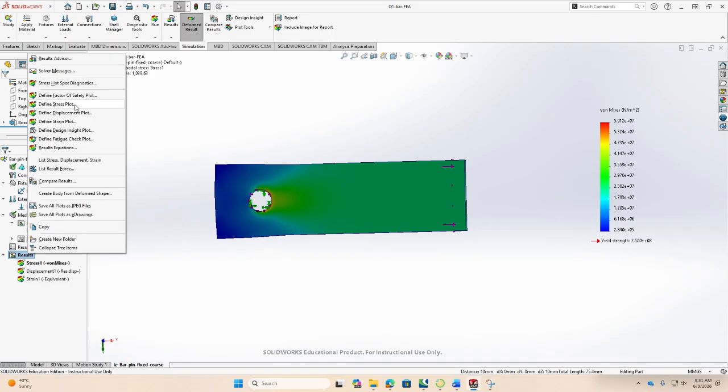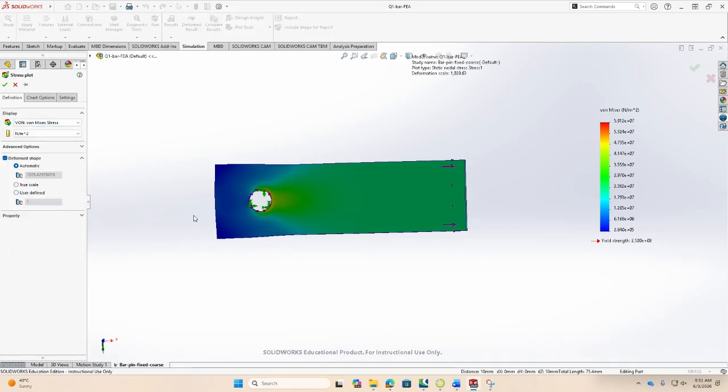Remember I told you the first step should be a sanity check. The quantity that I can compare is, number one, the stress. The stress through my hand calculation, which I know most reliably, will be based on the gross stress measure. I did not do this calculation yet in the hand calculation, but we can do that very quickly right now to check this. So let's now plot stress, normal stress along the x-axis.